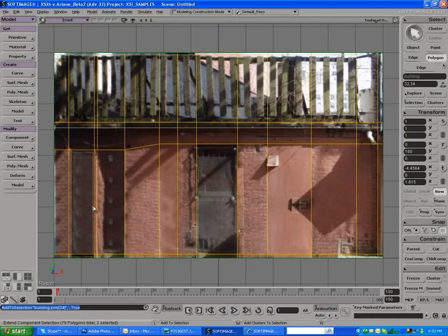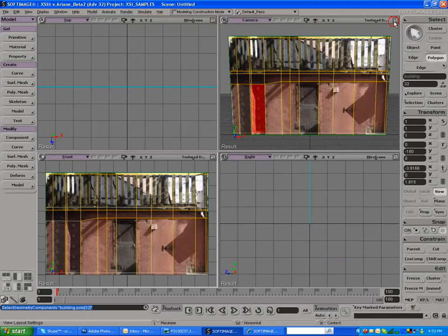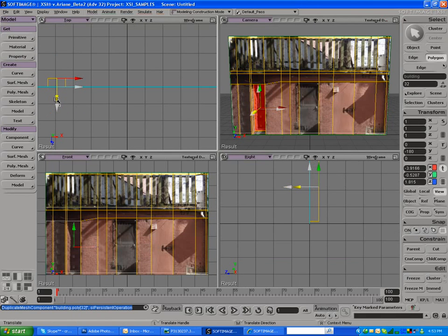I can just pick these two objects. We'll start to pick this one. It's really got a big indent in there. So we'll just go there and pick that, and we'll hit Control D. That will duplicate the face. We'll go to the Move tool and just move it back. And you can see now we have some depth there.